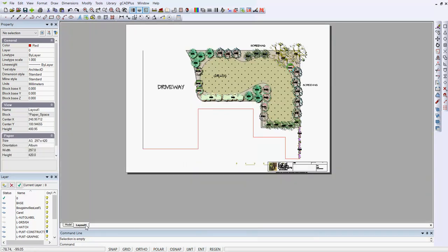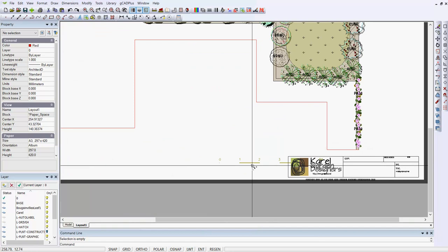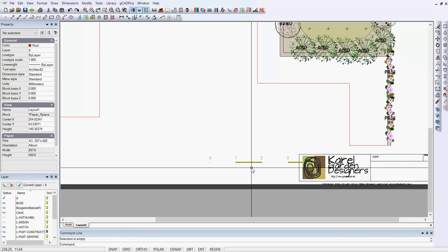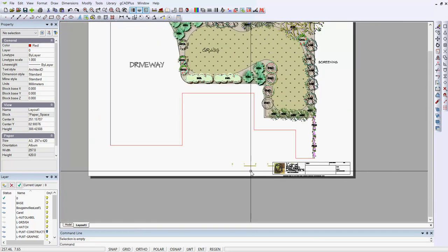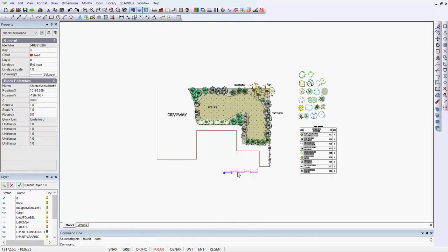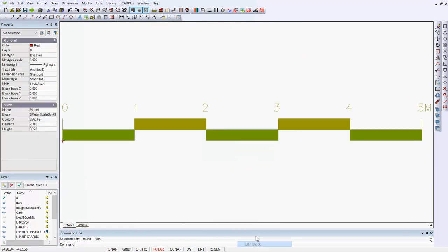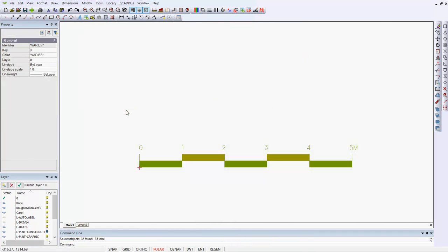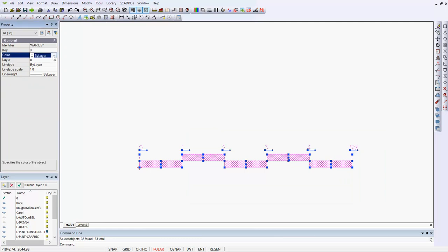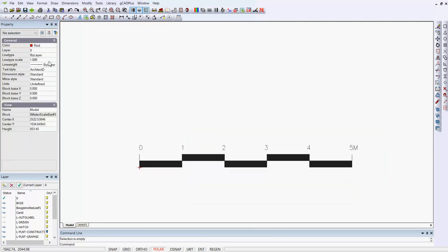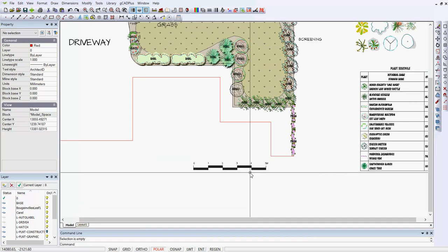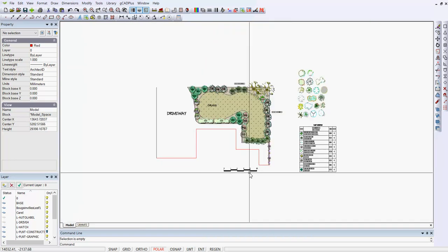indicator as well. So if we go to layout, you can see we're not quite positioned the way we want, and it's also not standing out as well as that logo, that bar should. So let's jump into there, edit it, and we'll move for the moment everything back to color by layer, and then close that block editor. So now it stands out very nicely.